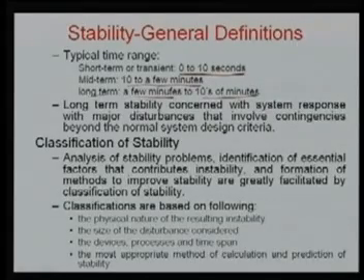Long term stability is concerned with the system response to major disturbances that involve contingencies beyond the normal system design criteria. Now, one thing we should always keep in mind: it is not possible to design a system that can sustain all possible contingencies, all possible faults. If you were to design a system that can sustain all faults, all types of trippings, all considerations, it would be very, very expensive. So, what we normally do is analyze the system with the most probable and credible contingencies in the system, and based on that we analyze the whole stability phenomena, be it transient, small signal, frequency or voltage instability as well.